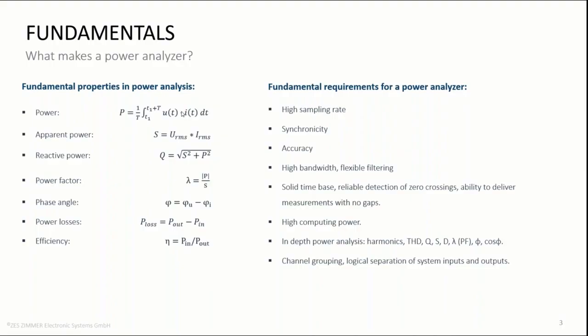In design, that means that the current and voltage signal paths need to be, if possible, identical, since even some millimeters of conductor can introduce nanosecond delays that will harm the synchronicity of u and i. Design also needs to consider the effects of all connections that may increase impedance on the signal path even slightly and cause unwanted phase shift on one of the signals.